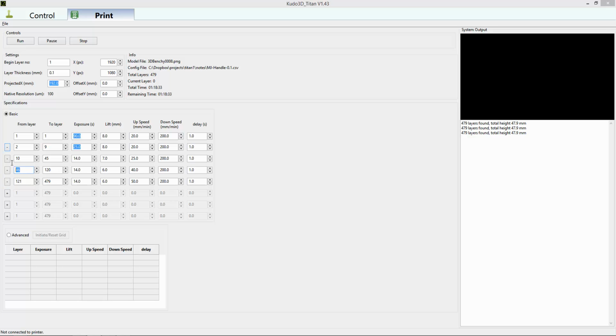Let's say I set this to 40, right? So now this is messed up because these two layer settings overlap. As I work my way down, right, and then I come back, this is going to automatically correct itself to 46, which is the correct layer to come after 45. And so I do this just to make sure that I don't get any discontiguous layer designation error messages when I print.